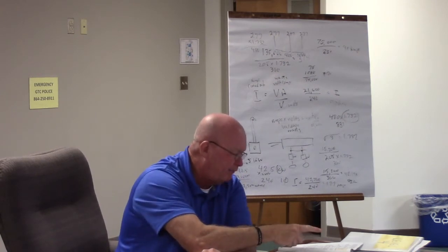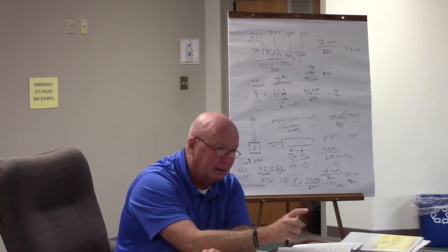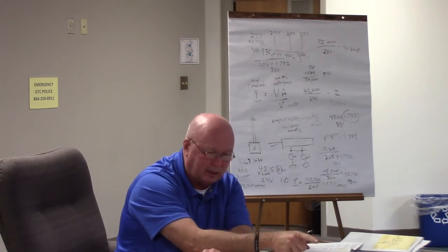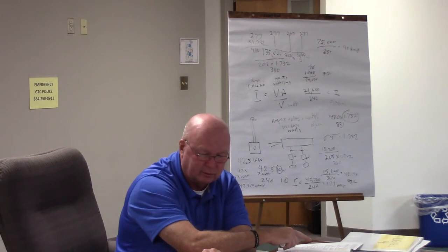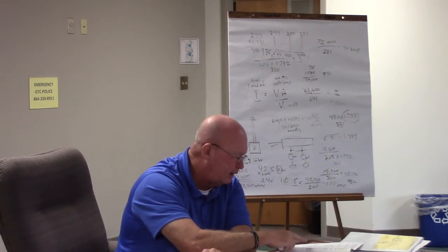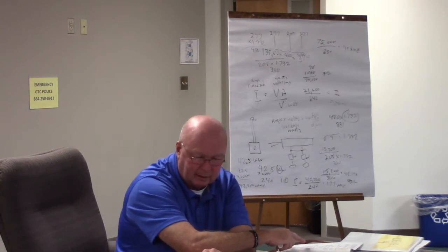Then if the termination is 75 degrees, we could actually use number 3 wire, couldn't we? If not, if you read there, then number 1 would be required.